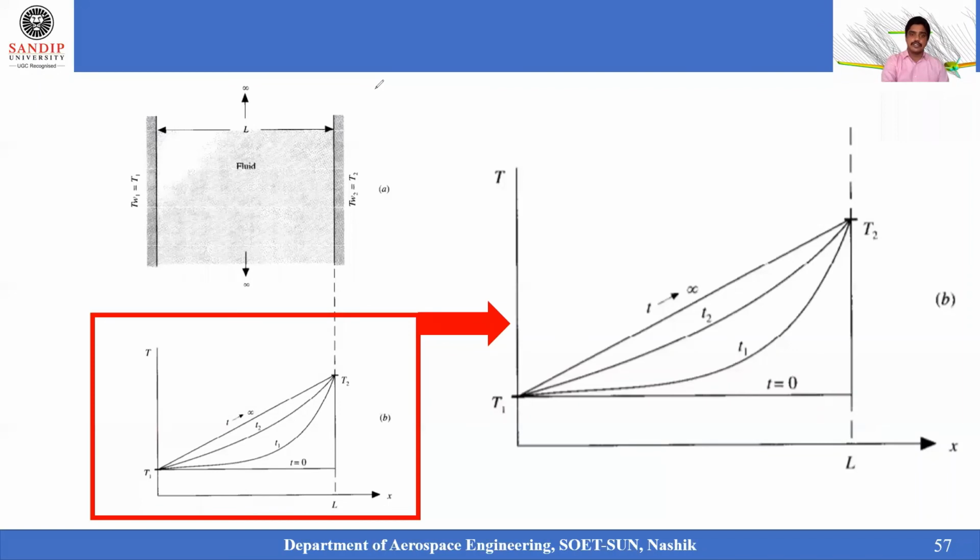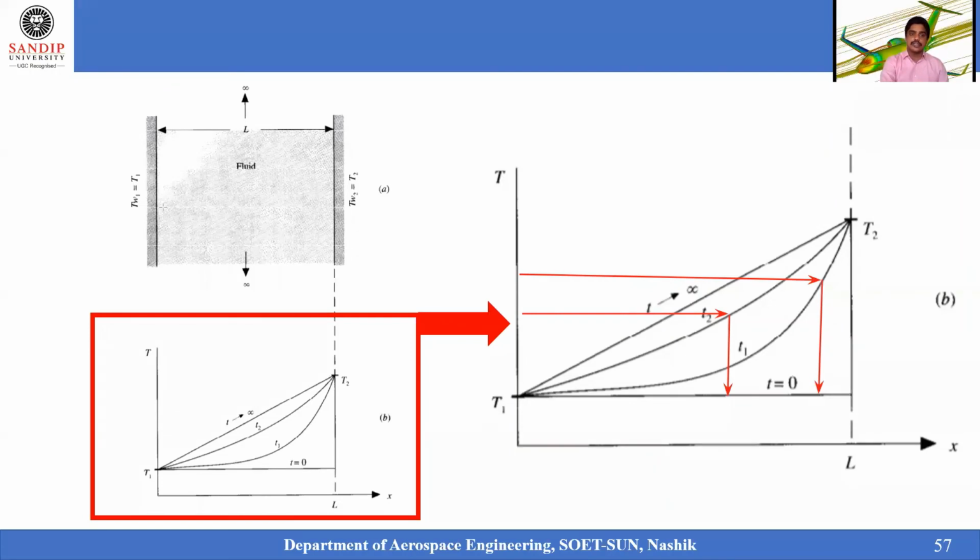That is what we have seen in the governing equation: with respect to time, how the fluid flow problem is varying. How the heat is transferred along the length L, from this point to the other point, by conduction with the fluid problem, is addressed here. This type of problem is generally parabolic in nature.